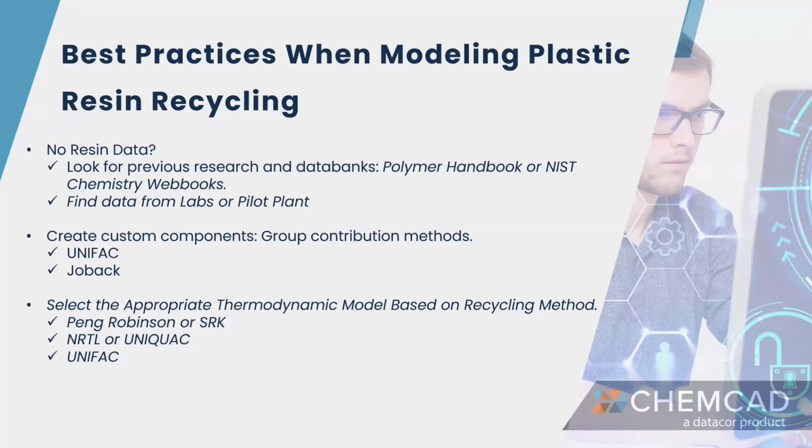Another important decision to make is the appropriate selection of the thermodynamic model, depending on the recycling method and the process that you will be simulating. For example, Peng-Robinson or SRK might be suggested for processes such as pyrolysis or gasification.